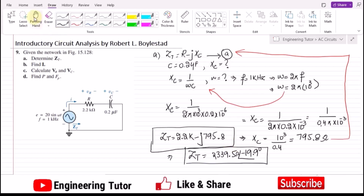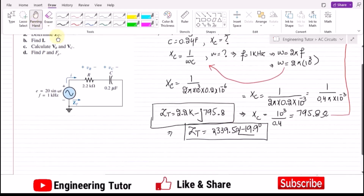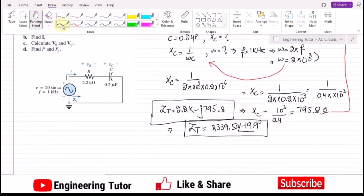Now similarly, in order to find the value of current, I can see that the value of current is basically E divided by Z total. Do I know the value of E? Yes, but that is the peak value of the sine omega t.